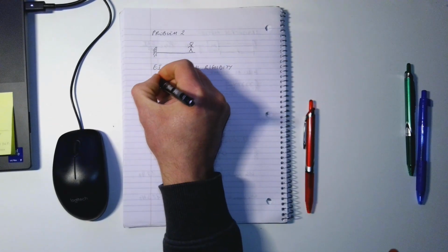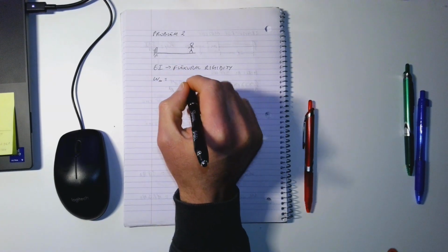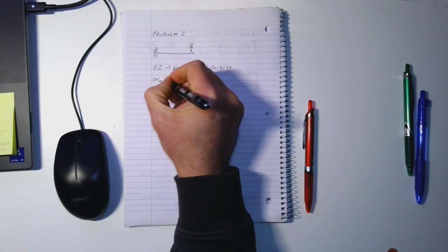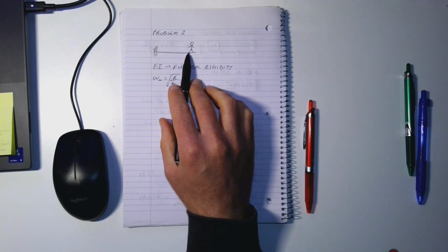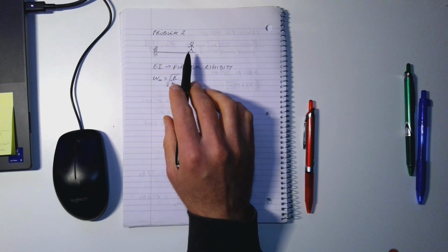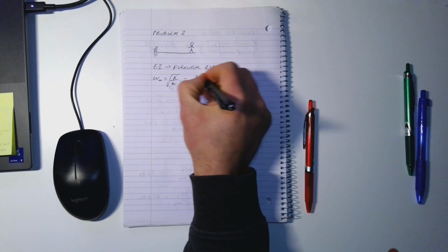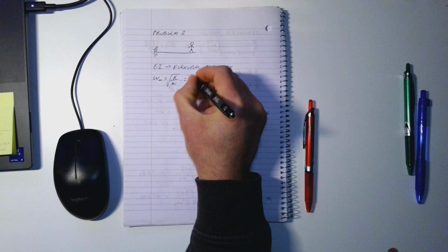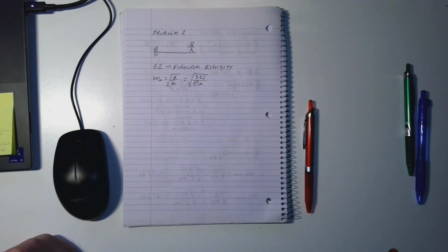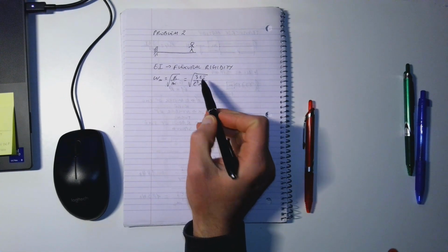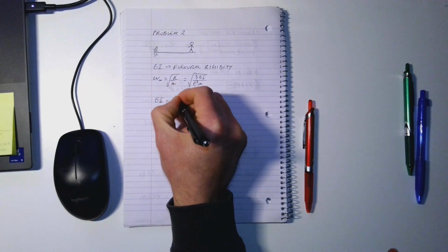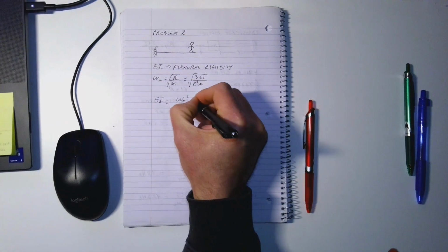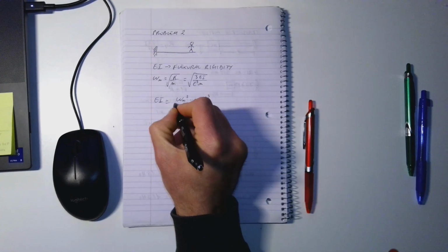So we start from the definition of the natural frequency. We already know that it's the square root of k over m. We know that for the transverse motion, the value of k is 3 EI over L cubed. So we have 3 EI. So we can plug this quantity here, and then, as we just said, we can simply work backward. So basically, this term here, EI, is what we need to obtain. So when we go through a couple of steps, what we obtain is that EI is equal to omega n squared times m times L cubed divided by 3.